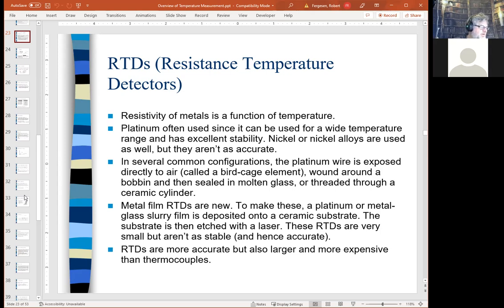For instance, the book on the bottom of page 47 has a picture of a thermocouple with a standard yellow plastic connector. And if you use that connector with that thermocouple, then you'll get a very accurate reading. And you don't want to goof around with your own connections. You can't just clip off a thermocouple wire and throw a wire nut on it to another wire. You will run into a problem.